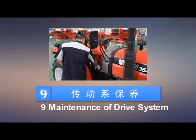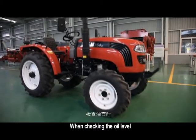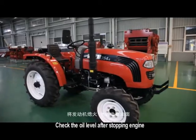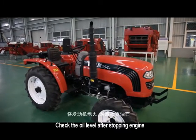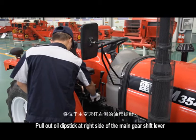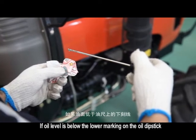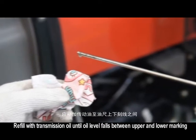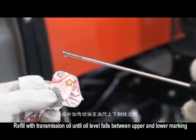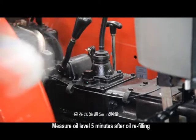9. Maintenance of drive system. Attentions: when checking the oil level, park the tractor on the level ground. Check the oil level after stopping engine. Pull out oil dipstick at right side of the main gear shift lever. If oil level is below the lower marking on the oil dipstick, refill with transmission oil until oil level falls between upper and lower marking. Measure oil level 5 minutes after oil refilling.